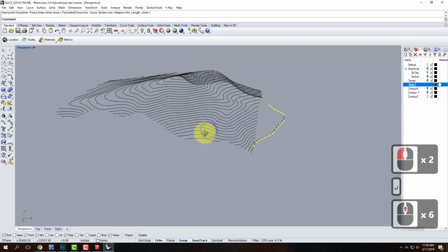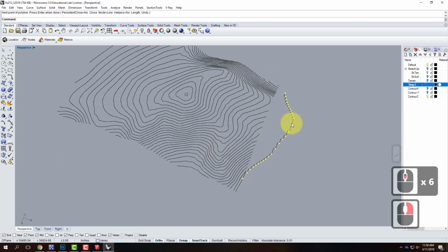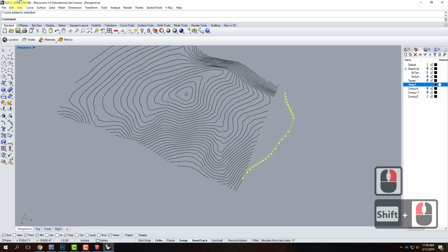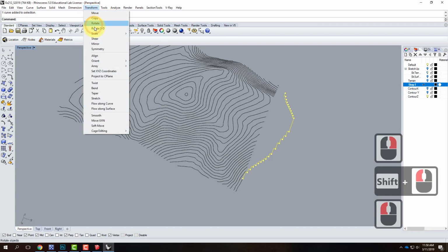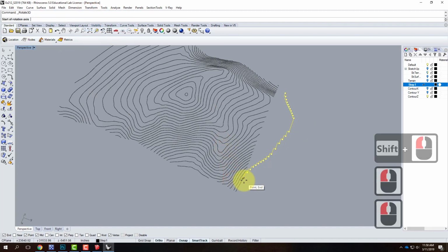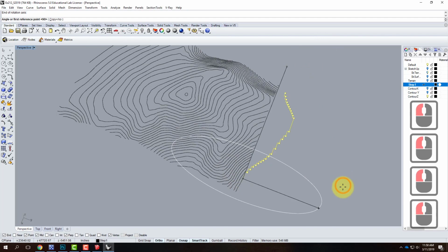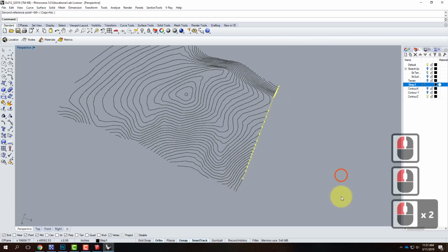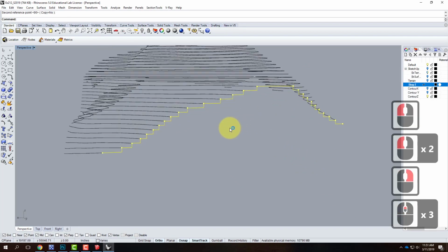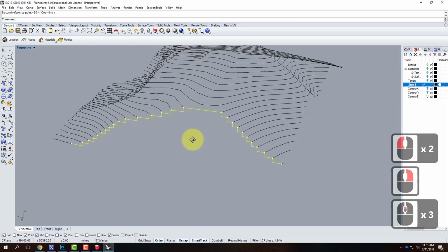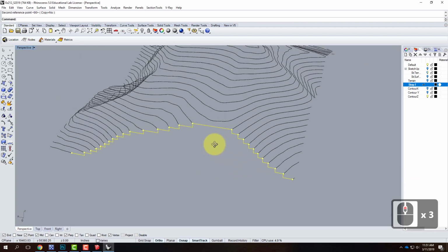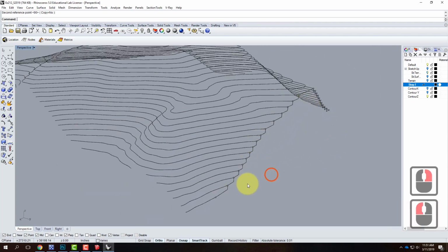When I'm done with all of those steps, I'll select them and the points. I'll do another rotate 3D. So I'll go back to transform and then rotate 3D. Start at the same point and fold this back up to where it's along the edge. And we can kind of confirm that, yeah, that looks the way it should. So that's one method. With the points, you fold it flat and you draw.